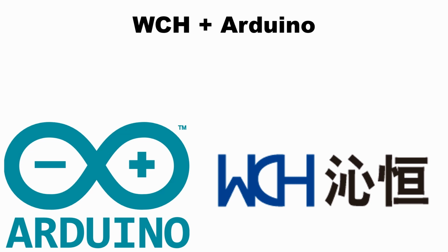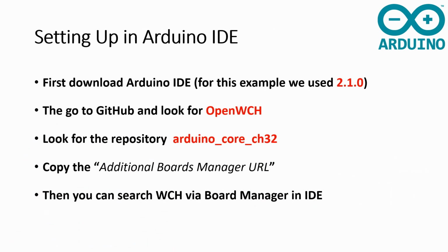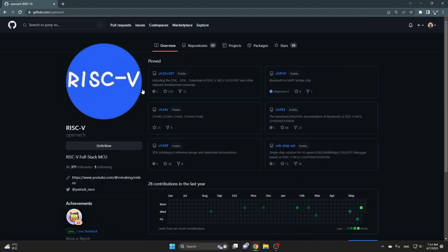So let's begin. Step 1, how to set up this development system with Arduino. As I said before, provided you have the WCH Link and a CH32V003 development board, then you can begin programming Arduino with WCH. So the first step is you need to download the Arduino IDE, and then the next step is you need to go to GitHub and search for OpenWCH, which is the GitHub repository for WCH related code.